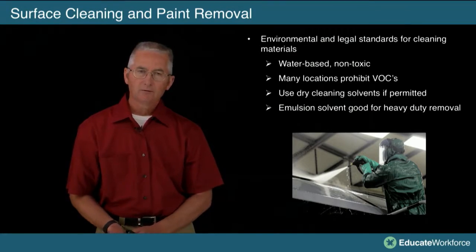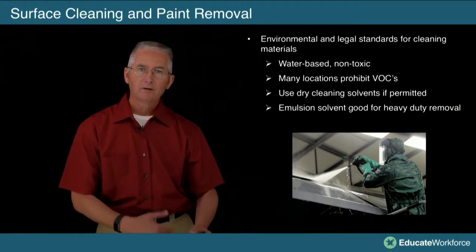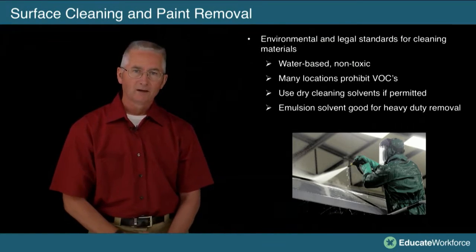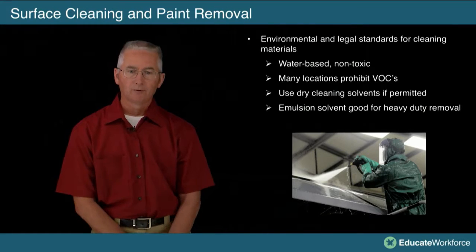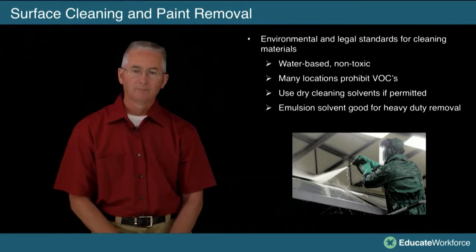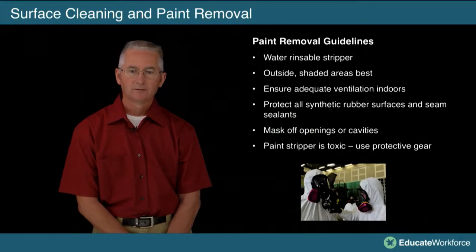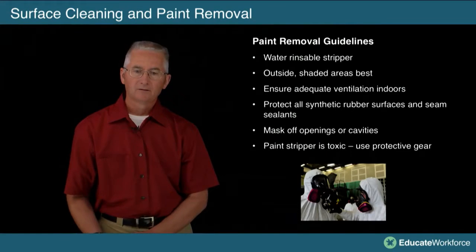Emulsion type solvents are very, very good for removing grease before you get started. You want all your grease and oils off of these surfaces before you start putting these paint removers on the surface. The guidelines.